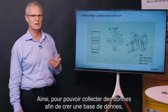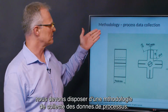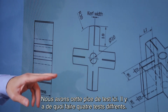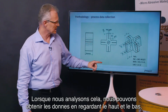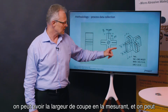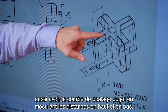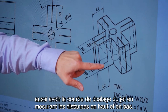To be able to collect data, to make a database, we have to have a methodology to collect process data. We have this test part here. It has room for 4 different tests. When we analyze this, we can get the data from looking at the top and the bottom. We can look at the width of the cut by measuring the width, and we can also see the lag by measuring how far the jet curve goes into the part at the top and at the bottom.